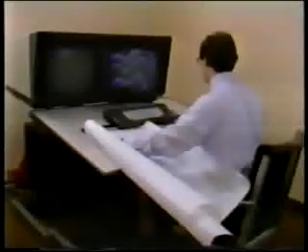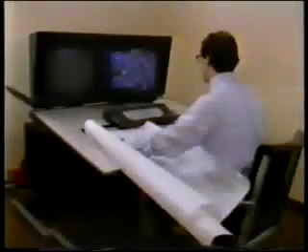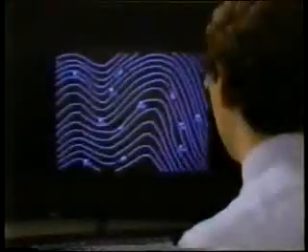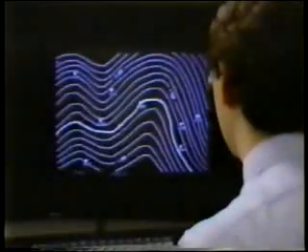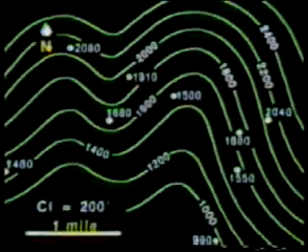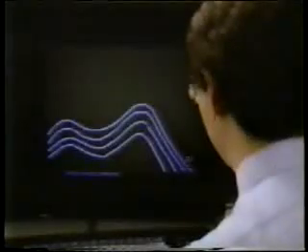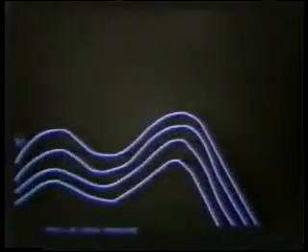Mechanical contouring, which can be programmed into a computer fitted with a mechanical plotter, is one method of constructing contour maps. Contour interval is selected, and contour lines are interpolated with equal spacing and linear slopes between any two control points. This scheme has much to recommend it because it takes the human bias and tedium out of map making. But there are several pitfalls to this method.